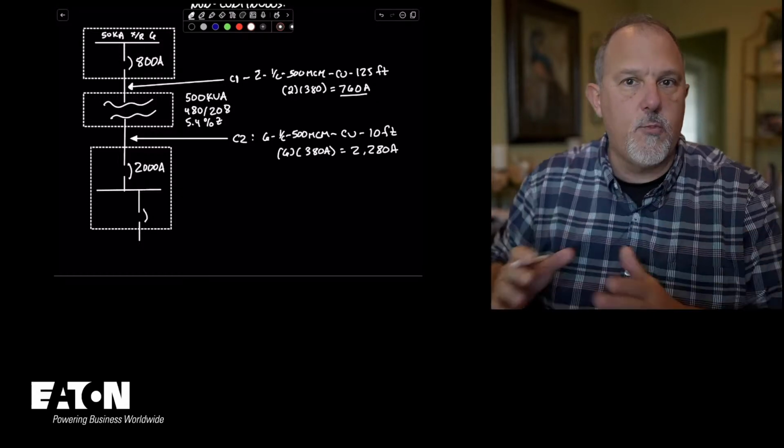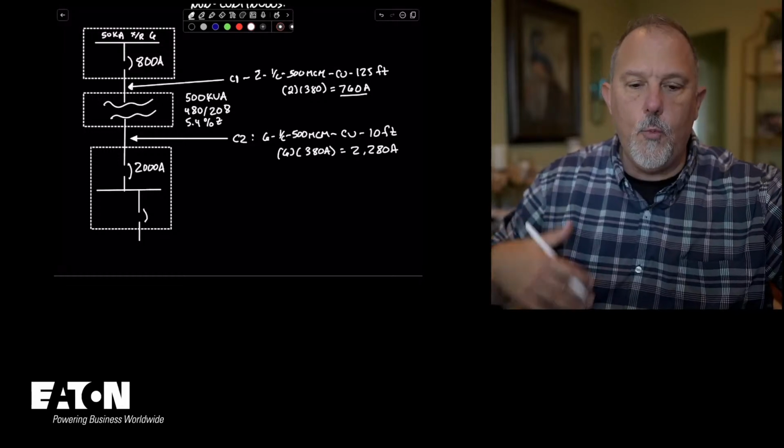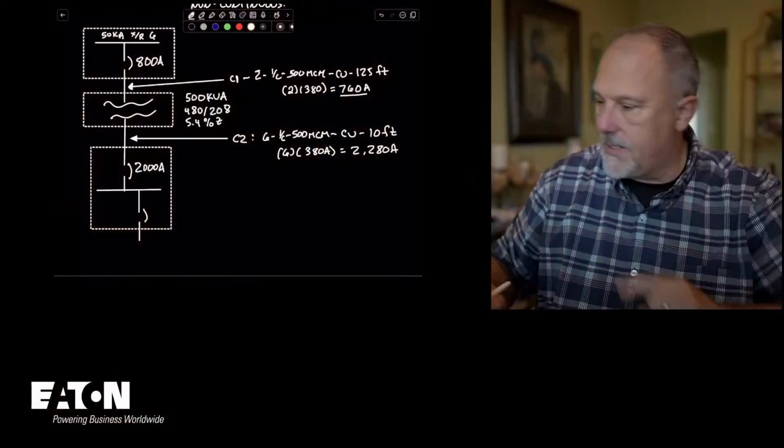And it really doesn't matter, because the process that we're going to walk through will be the same regardless. So if you pick a different conductor, just use different impedance values, but the math will all be the same. And what we're going to do next, now that we have secured the one-line diagram, is create the impedance diagram. We're going to convert all of the components in here to an impedance. And then we're going to use Ohm's law. But the next step is the impedance diagram.